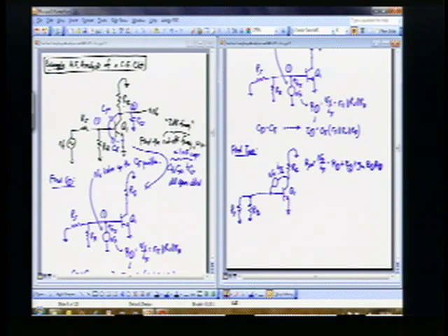All right, so if I go ahead and apply this equation, then I can write my R mu naught directly here. That's just going to be, first of all, R1. What's this R1 circle? Can someone tell me? RS. Excellent. So it's RS parallel RB, but there's one more. R pi. Yeah, parallel with R pi. Remember, it's in shunt with that node there.